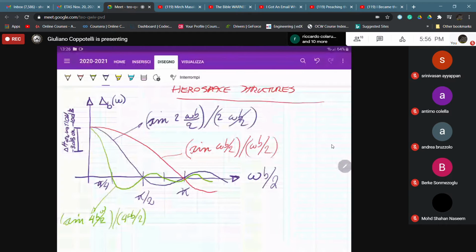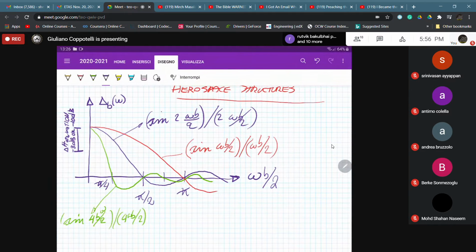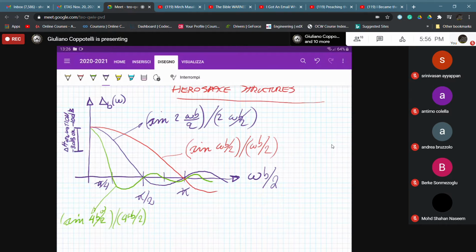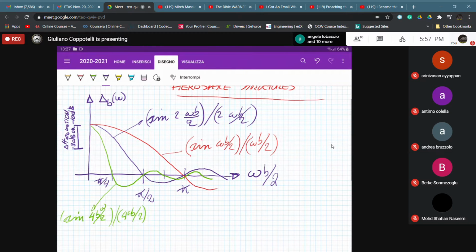That reduction, once again, is telling you what is the attenuation that you are accepting, and therefore giving you information that this attenuation is the maximum that you can have before saying that the signal level is too low, the signal to noise ratio is too low.